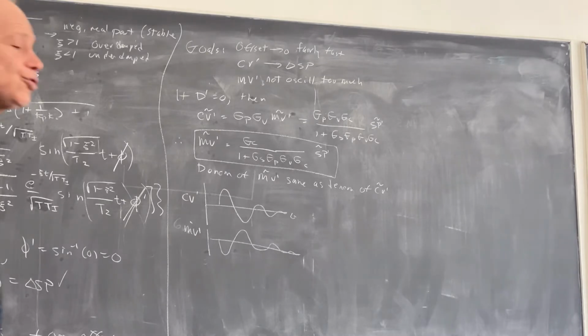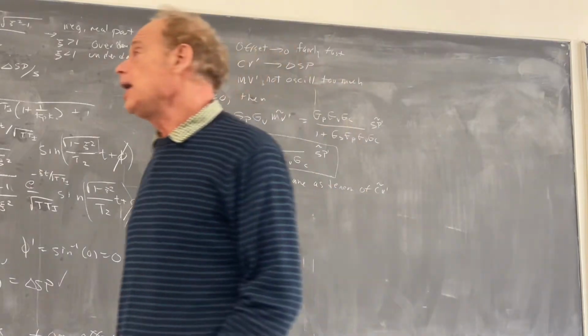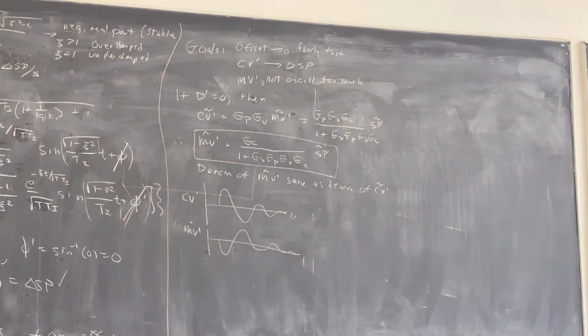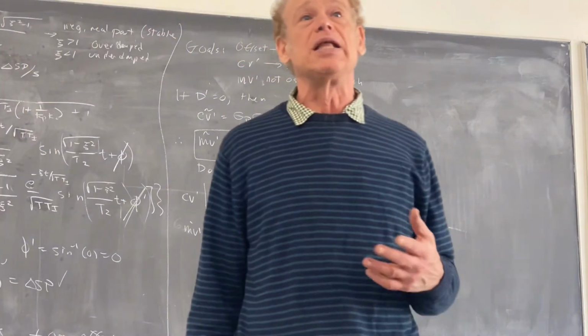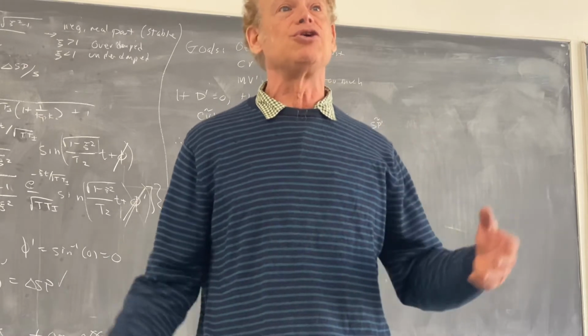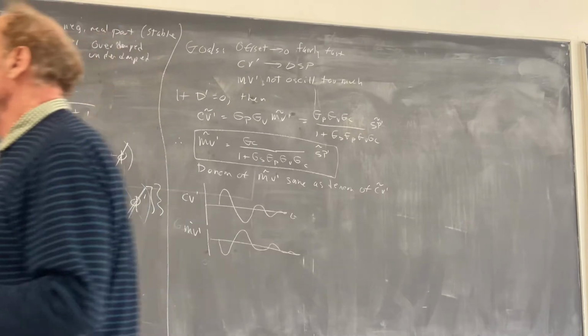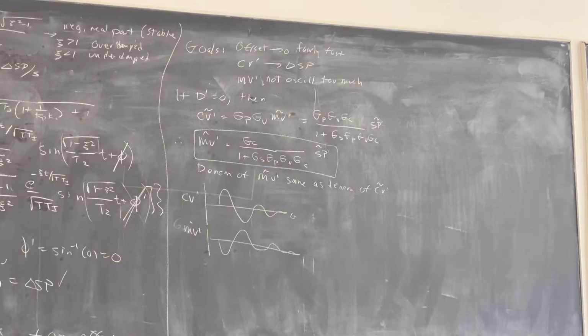So what you would do today is, if you decide to use a PID controller, in order to get the best value, you would need a model of your system. You'd have to write out your model completely. And presumably, we were doing our analyses by linearizing the models. Presumably, you would keep the models nonlinear because you have a nice computer that you can solve nonlinear equations. And you would try to solve the equations for different values of Kc, Ti, and Td.